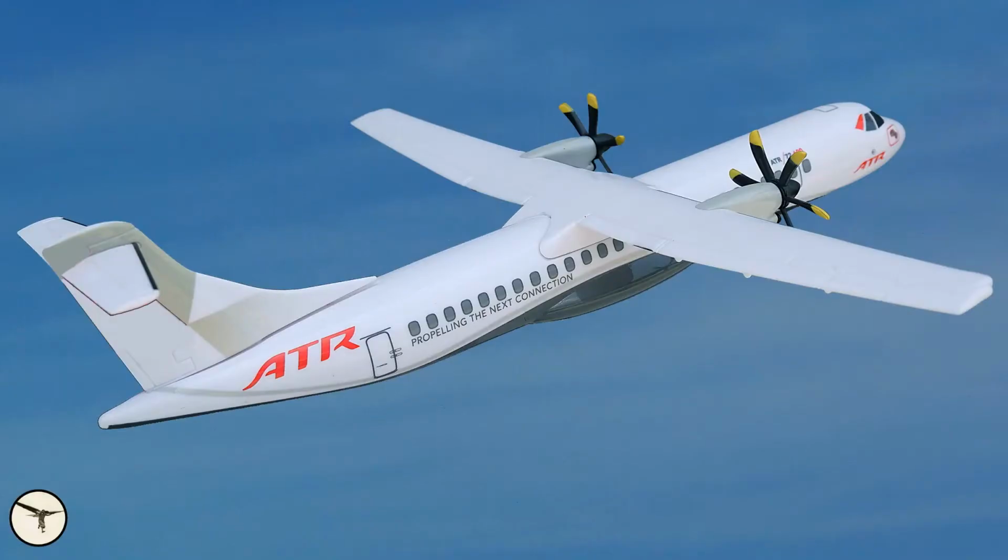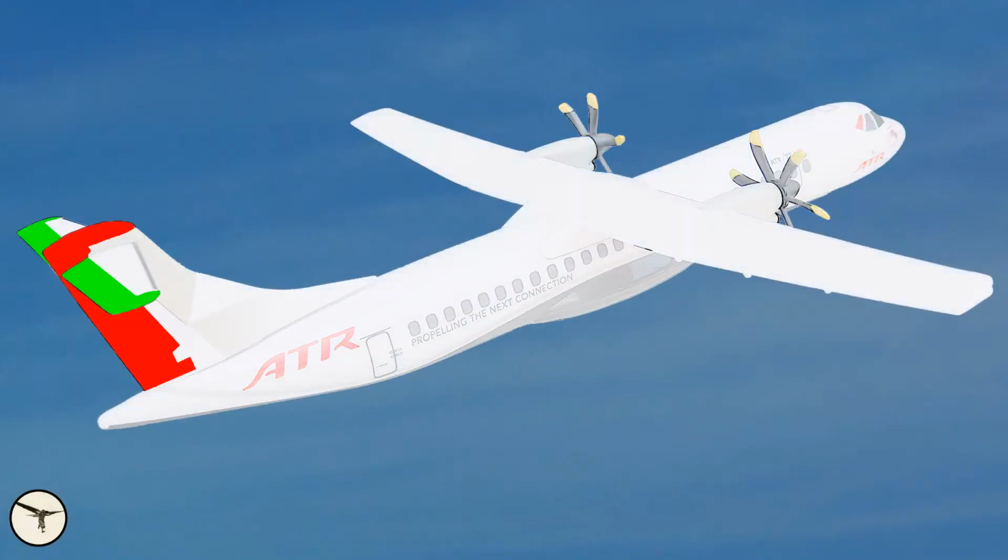In this video, we will have a look at the flight controls in ATR. They are divided into primary and secondary flight controls. With a few exemptions, they are pretty straightforward. The primary flight controls are elevators, rudder, and ailerons. All of them are manually operated. They can also be operated by the autopilot. Each one of the primary flight controls have electrical trim.